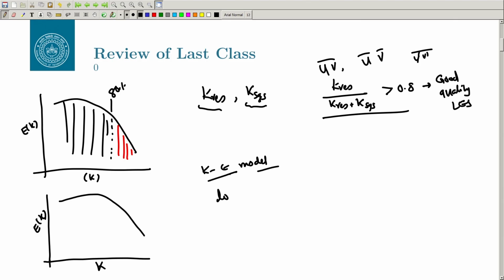How do you calculate that? Remember, we discussed in the eddy viscosity models that all these models have a nu turbulent, or nu eddy. Eddy viscosity is basically some factor of L naught into U naught, some length scale and some velocity scale, because its unit is meter square per second, and this is meter and this is meter per second.